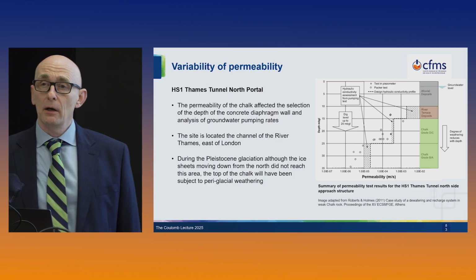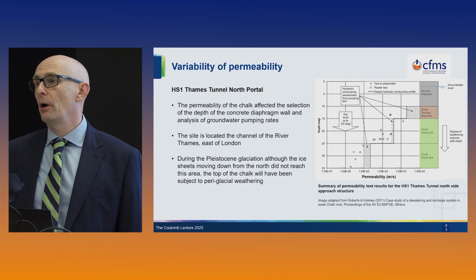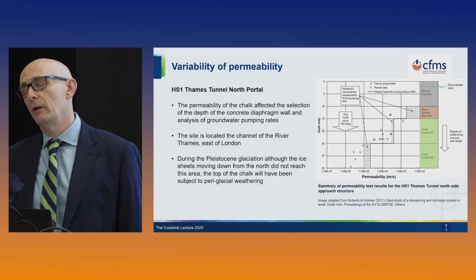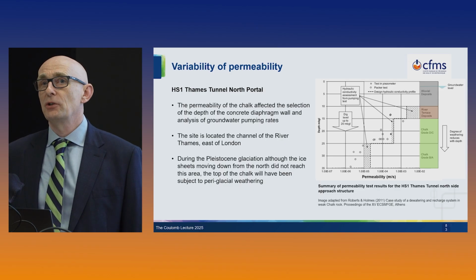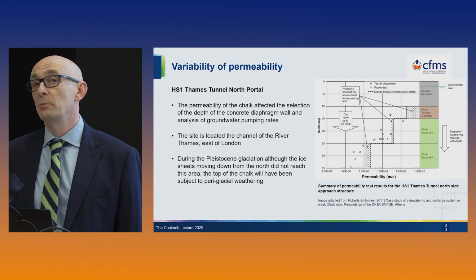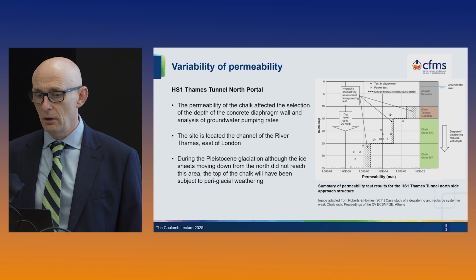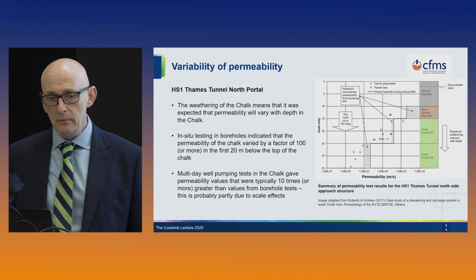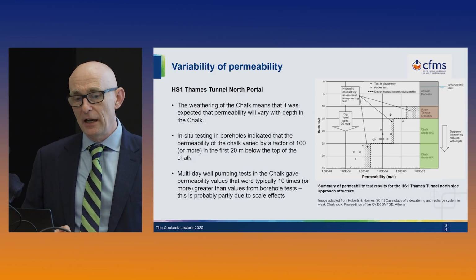But this area, when the chalk was exposed, will have experienced what are called periglacial weathering, extreme freeze-thaw conditions over thousands of years. So there's evidence that the top of the chalk is very highly weathered and has become what we call structureless. So any natural structure of the chalk has been disrupted. And that's quite common in several parts of the UK. And so the weathering of the chalk meant that it was expected that the permeability will vary with depth in the chalk.